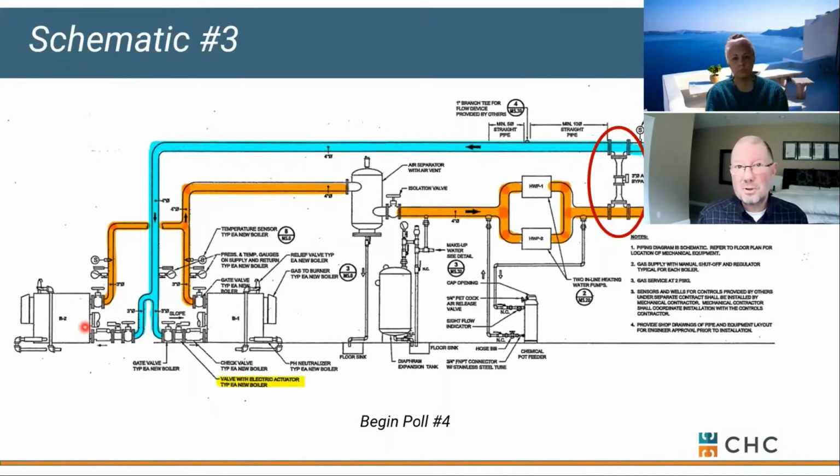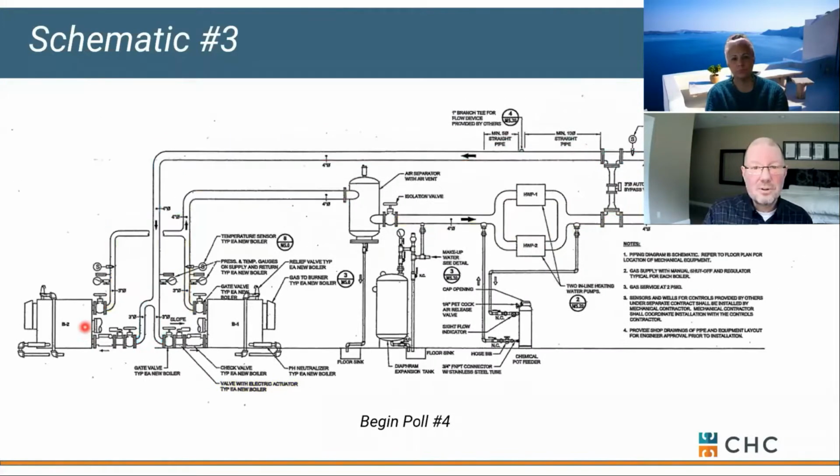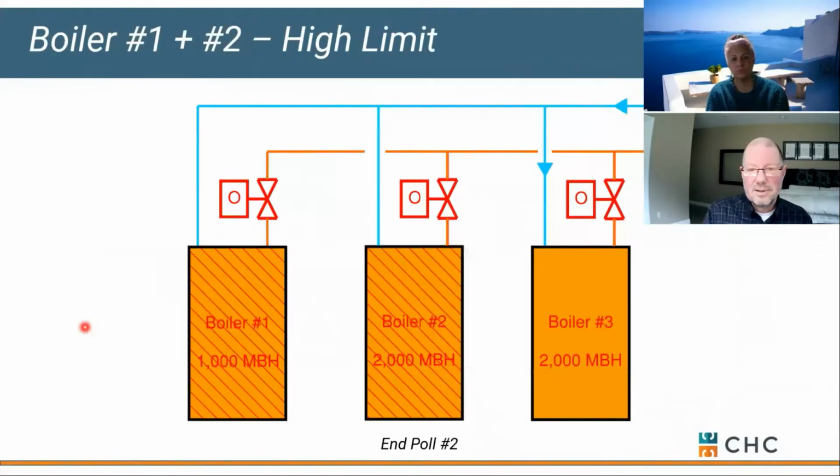But in general, yeah, if you go direct return, you may run yourself into some trouble, depending on the size of the equipment and the pipe size. The example that I showed earlier on direct return, this guy right here, there was not a lot of flow in the system, which was another downside. The engineer laid this out based on a 70-degree delta T in the system, so there wasn't a lot of flow to deal with to start with.